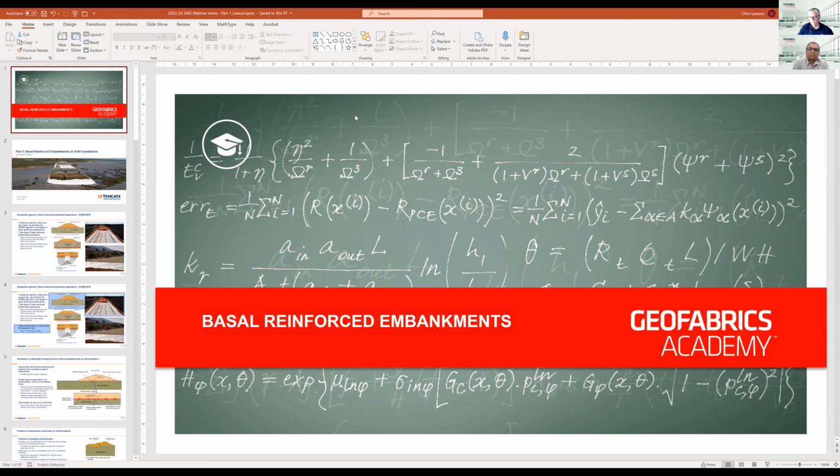So you've got to either assume that and know that, or maybe you can lay out the reinforcement so that there's some sort of redundancy in the reinforcement that gets you over that problem. For example, you may put some reinforcement at different angles on the ground to be able to transfer the loads around where you've actually cut it. But it depends on what your application and what you're doing, really. But if you just cut the reinforcement, then there's no strength transfer.